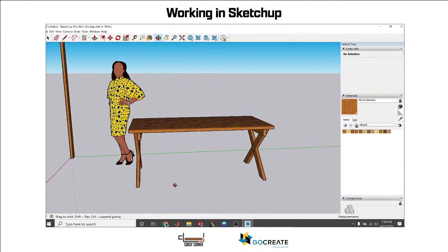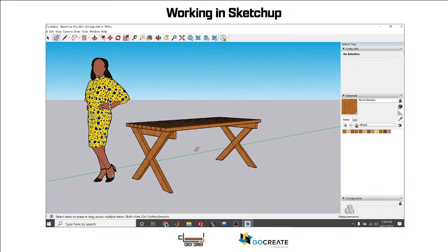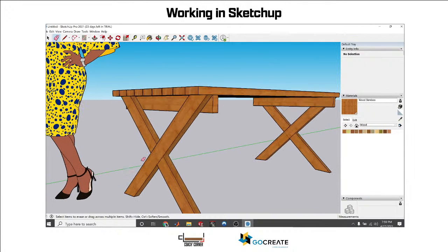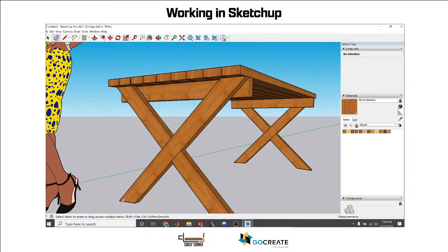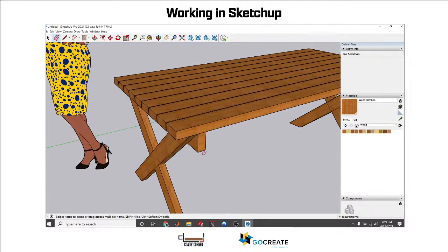And then you get an idea, like, okay, well, these are how I would cut things, and you measure, like, I'm gonna cut 45 degrees there, 45 degrees there. I'm gonna notch halfway through this one and halfway through this one to make those lay on top of each other. I'm going to use screws here and here, here and here. Screws all along this deck here, and obviously all along that deck over there.